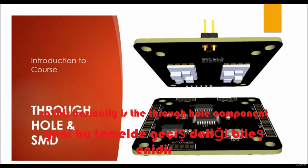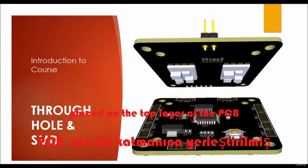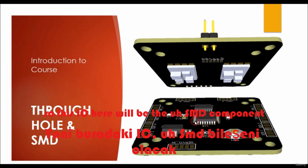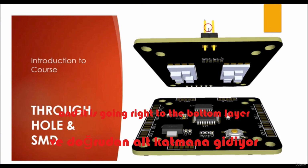So this basically is the through hole component. Also you can see that this IC here is placed on the top layer of the PCB and it's not going to the bottom layer. So this IC here will be the SMD component and this connector will be the through hole because it is mounted on the top layer and it is going right to the bottom layer.